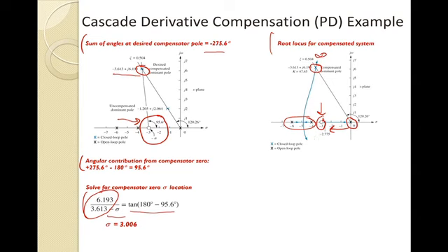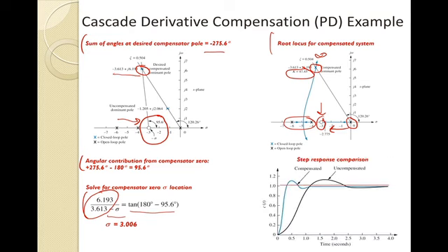And so that root locus will actually go through that compensated pole, because why? We know the angles. Once we included that compensator zero, it now equals an integer multiple of 180 degrees. And again, I can find the value of k for that. In this case, it's 47.75. Then what I could do is go back to the table, we'll do that in a second, and compare through simulation a step response.